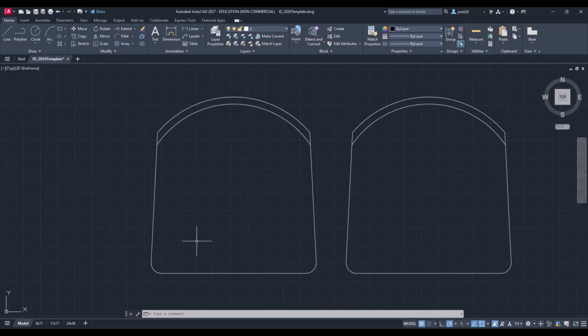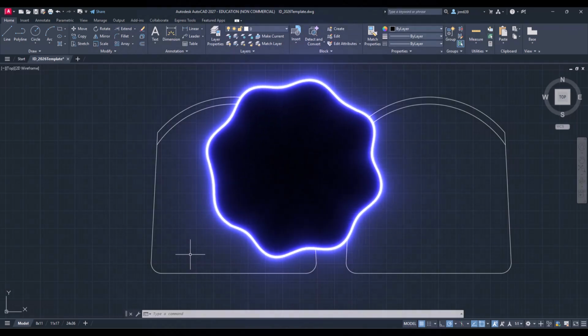This is another benefit to the block command. If you make multiple copies of a block and you need to change it, you just change it to one object in Block Editor and it updates all the other blocks. That's called working smart instead of hard. So my tip to you is once you draw a piece of furniture or a light fixture, go ahead and block it using the steps I gave you. This is how you maintain professional drawings.